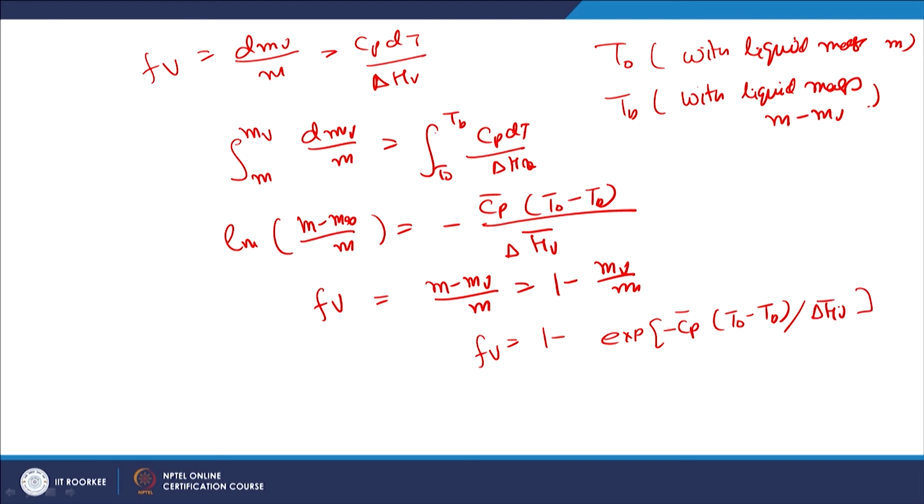Now, equilibrium flashing choking conditions. So, the fluid path length is greater than 10 centimeter. Now, choked pressure is approximately assumed equal to the saturation vapor pressure of the fluid in question. So, another aspect is that the liquid is stored above saturation temperature.